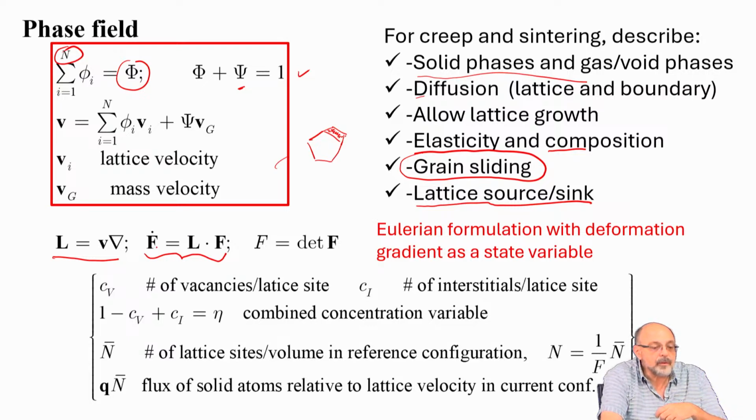But if I have followed my deformation gradient through time and solved for my velocity gradient, I can integrate the deformation gradient in time, and I can formally define the reference position of this newly formed lattice, because my tensor F maps dX into dx. Small dx is the current position, but I can do the inverse and integrate this to get my reference positions X formally.